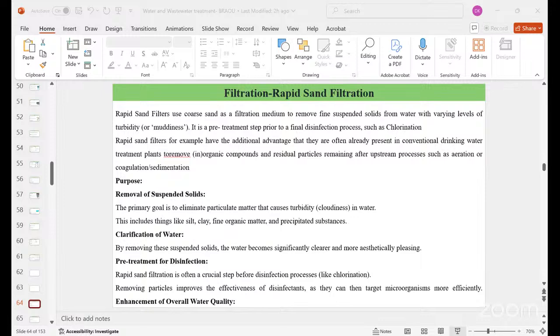So initially there will be the aeration process, then the sedimentation process, as we have seen earlier, by screening and by using coagulants, flocculants, and so on. The main suspended particles will settle down as grit particles, which can later be removed as grit sludge, or the sludge can be removed and reused for other processes or directly used for